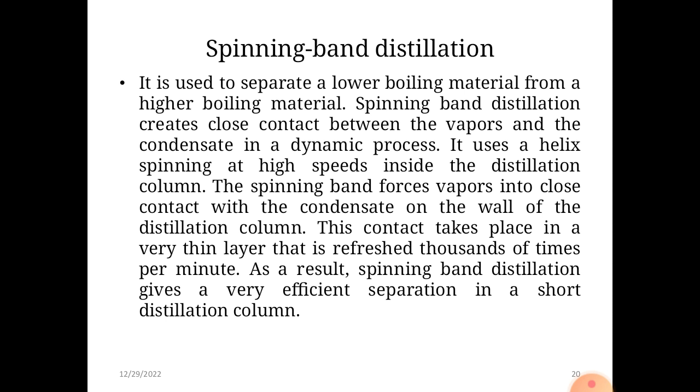So this is our spinning band, the general idea given there. Those which are heat sensitive or high boiling, highly viscous fluids, for them this method is used. It is very simple. Generally the column contains a rapidly rotating, motor driven spiral band.